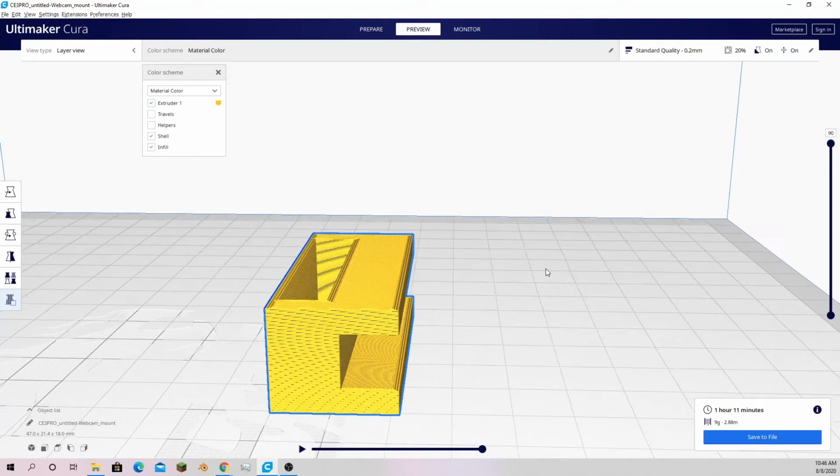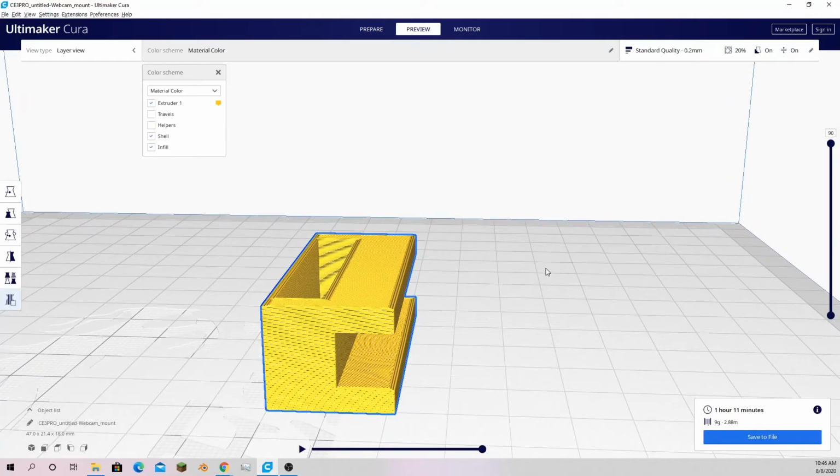And most of the time what the issues are is if you have stuff like non-manifold edges, where you have edges that don't create a face, where it's just like a circle without any thickness, for example, it can't print that. So also you have intersecting faces or vertices where faces intersect each other, and it can't just print one face and then the other face.